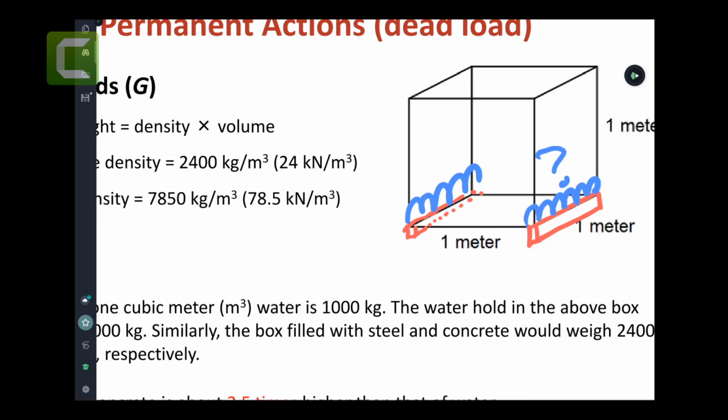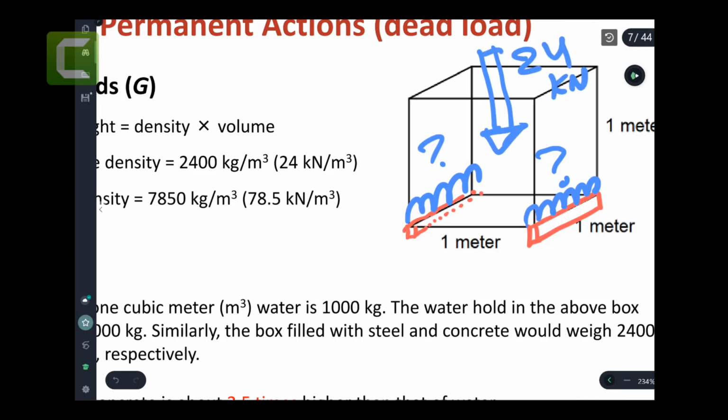So how do we find the loads on each one? One of the methods is to find the imagined point load, which was 24 kilonewton, which I did with you before, the one the crane was carrying. Then distribute it over the beam. Before I give you the answer, because you're going to have many examples to do, can someone tell me how I can work out the line load from the 24?